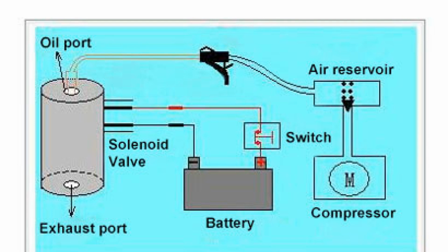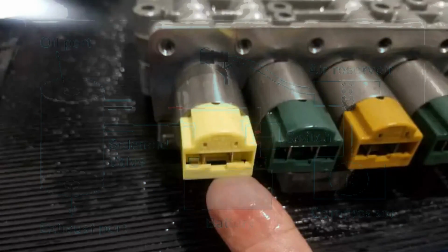Then VFS solenoids were also introduced. The design was simple and cheap in terms of production. However, there is a certain difficulty in operation. These automotive solenoids are considered to be very capricious. Plus, the service life, compared to linear ones, is noticeably lower. Low weight and high pressure contribute to rapid wear. Gradually, the valve begins to change the degree of opening, and therefore the computer has to read and process information